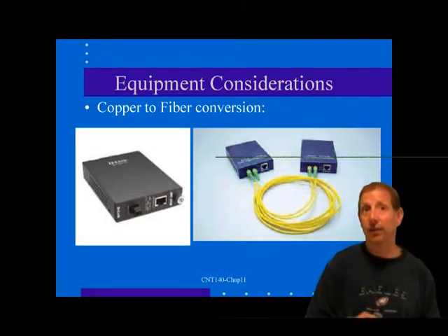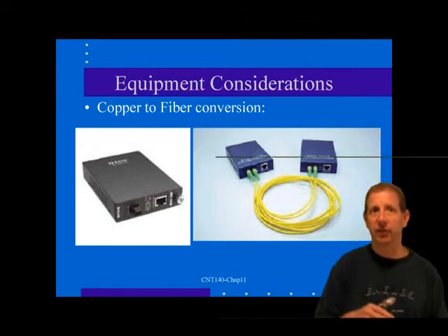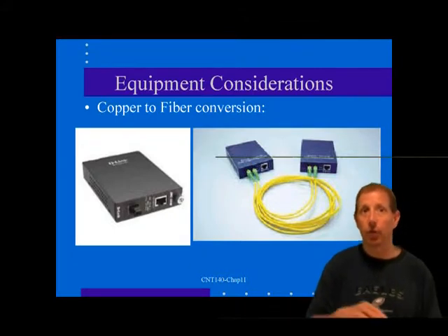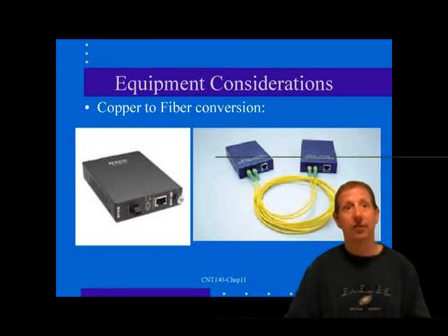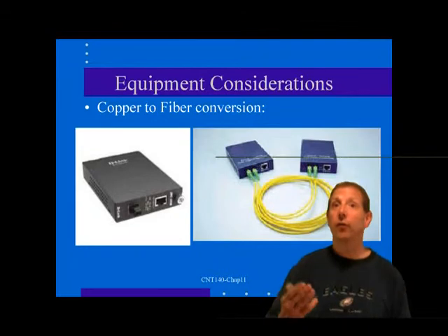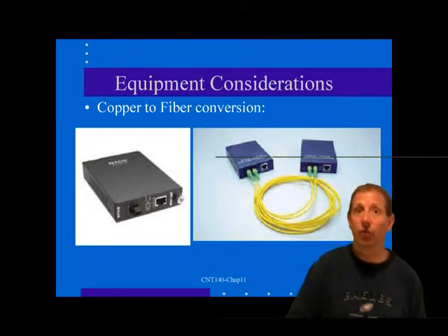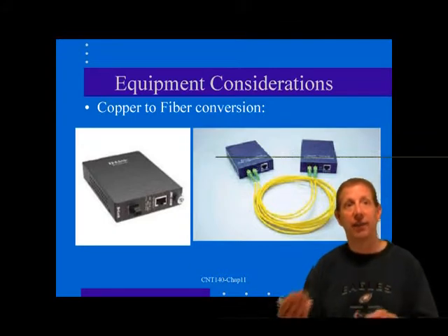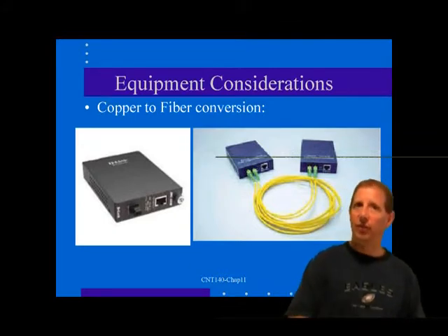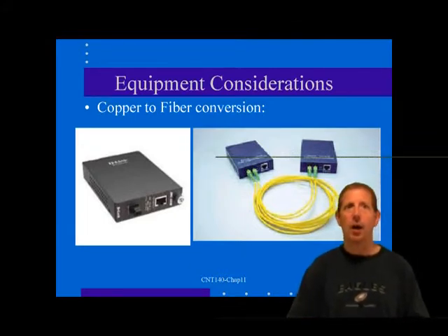Consider that the transition from a large 50 um fiber core to the tiny 4 to 8 um single mode core obviously wastes most of the incident light, unless you are fortunate enough to be using a laser source that has inadvertently positioned the beam to the center of the multi-mode core.